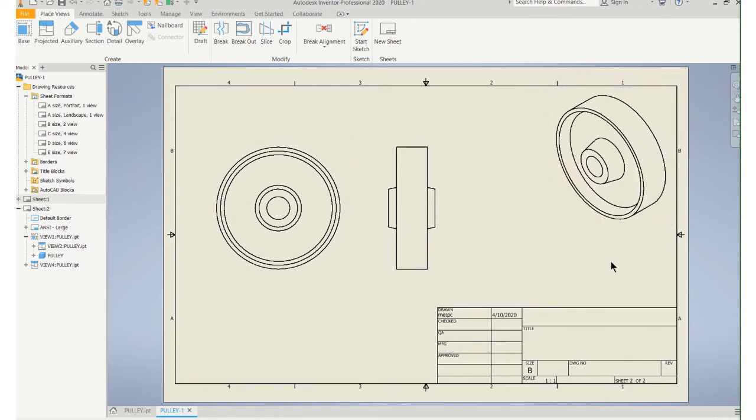I think the scale is about right here. So we can do this with two views, again, because the top and the right are the same. But don't leave the top view without a right side view. Again, look at your paper. Your paper is long this way, so you should put your views, orient them this way.